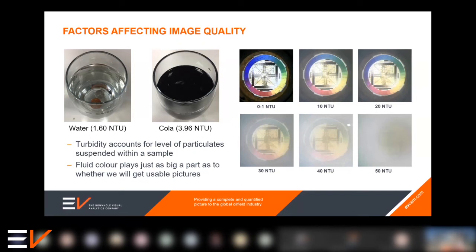So again, knowing this, we'll look at the well, we'll look at the objectives, we'll think about things that we can do that naturally occur in the well. If it's a multi-phase producer, for example, can we shut it in? And if it's a shallow issue, will we get a nice gas cap at the top that will allow us to take the images that we want? Or conversely, if it's deeper down, will we be in a column of water that could potentially be clean enough for us to operate in?